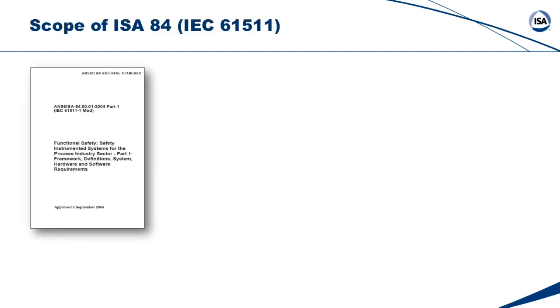In terms of safety instrumented systems, the standard that OSHA accepts is the ISA 84 standard, which first came out in 1996 as ISA 84. Then the IEC, the International Electrotechnical Commission, started writing functional safety standards as well, and they produced 61511 for the process industry. There's a higher level standard that covers all industries. There's one for nuclear and one for transportation and one for machinery, one for process. And the process safety standard is 61511, which was released internationally in 2003.